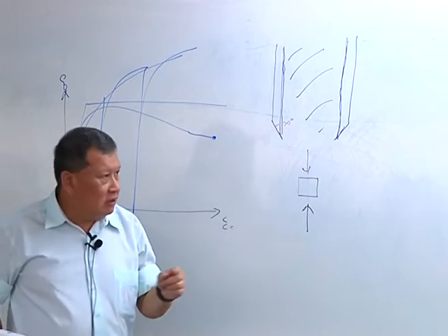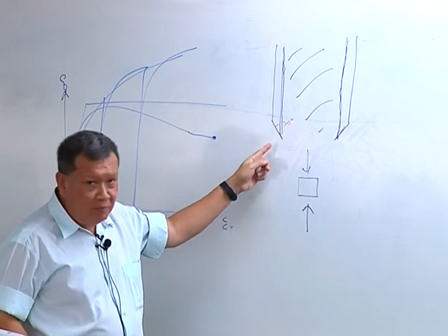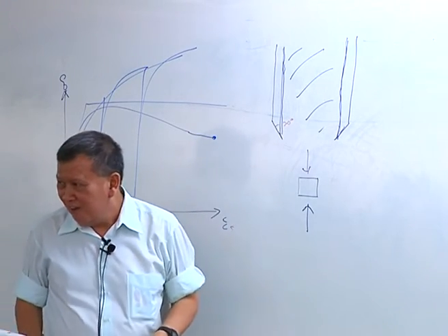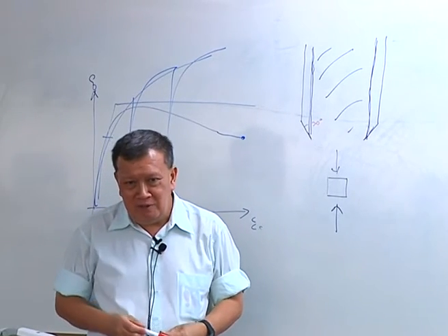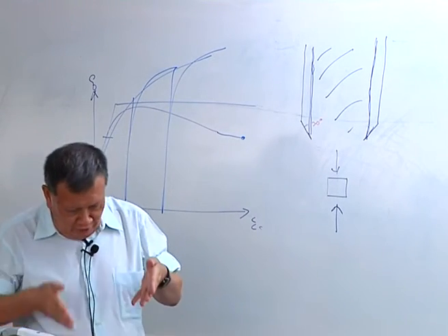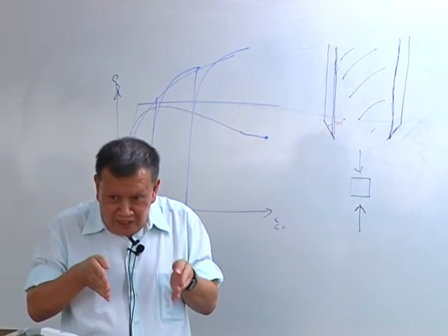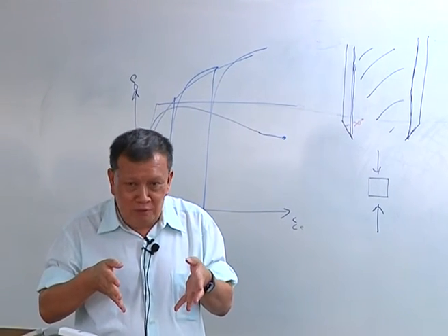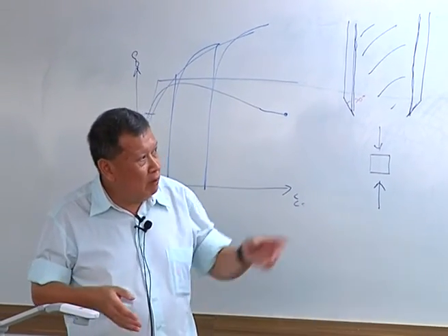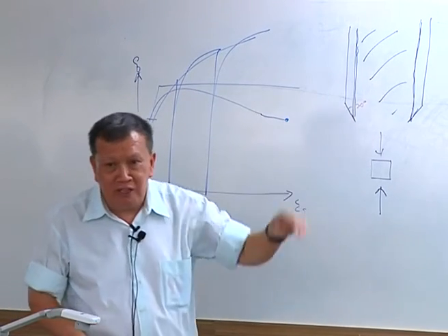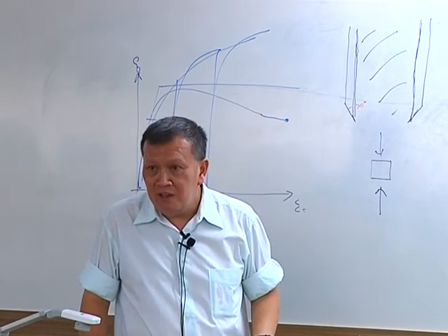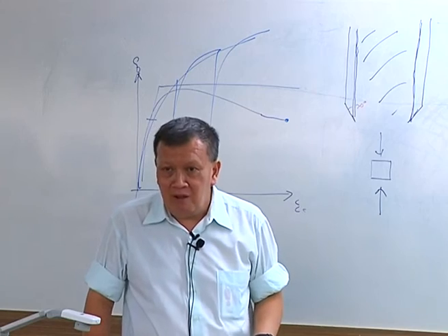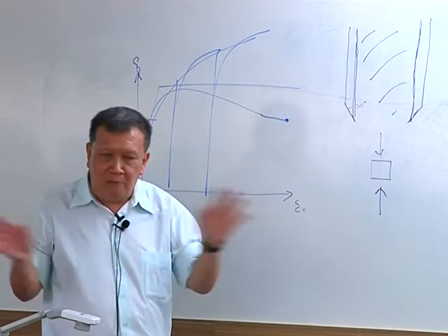The Japanese sampler tip is 6 degrees. It's a 6 degree tip. So it's a lot sharper, a lot thinner, and it is supposed to sample the soil. So when we work with the Japanese, these samples are all taken using a Japanese thin wall sampler, not the Shelby sampler. Okay, so with the Shelby sampler, it's all cut, completely cut.